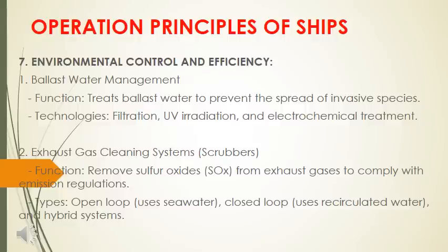Also, we have the exhaust gas cleaning systems, the use of scrubbers, to remove sulfur oxides, SOx, from exhaust gases to comply with emission regulations. The types of system we can use include the open loop, which uses seawater, closed loop, which uses recirculated water, and hybrid systems.